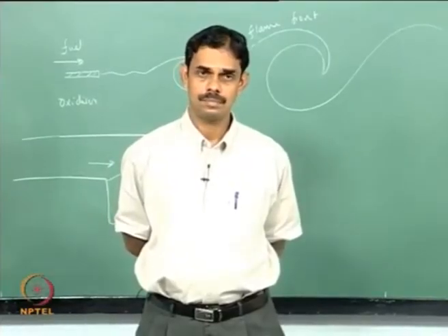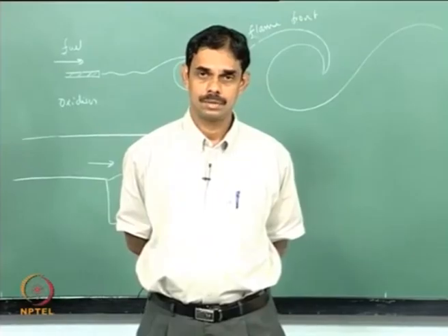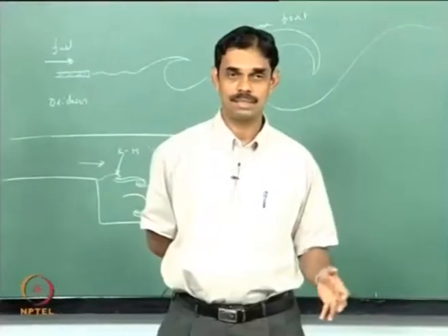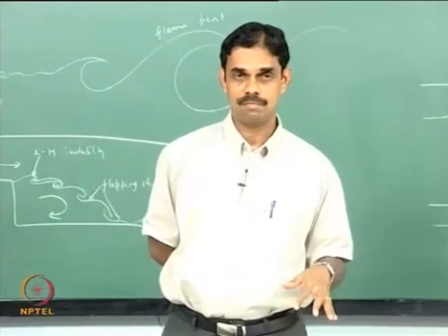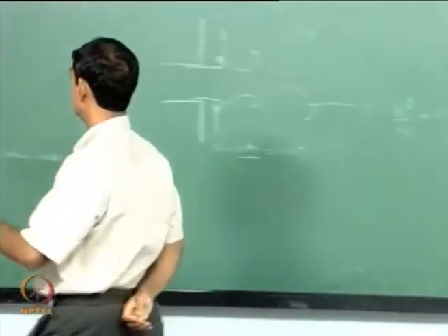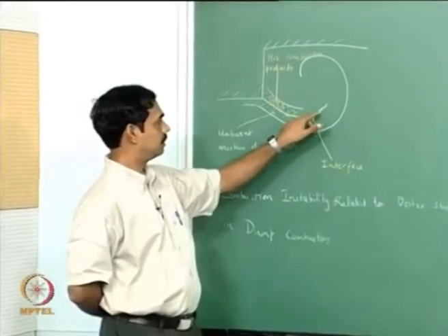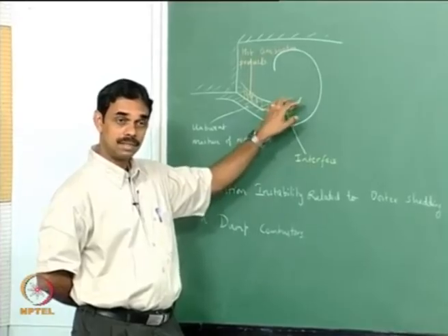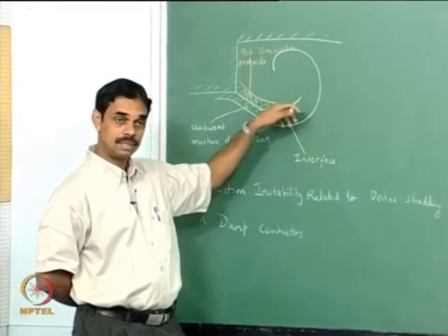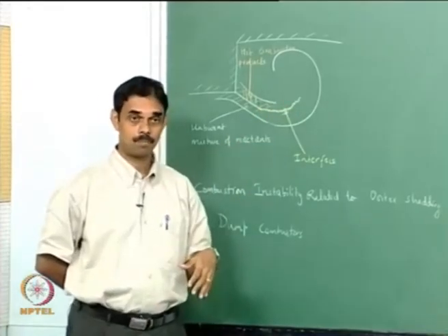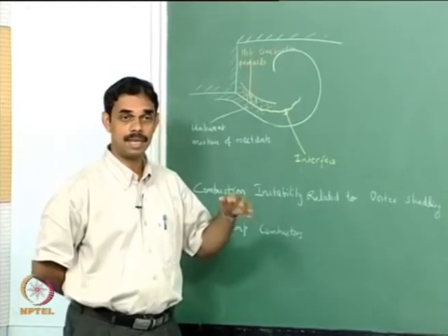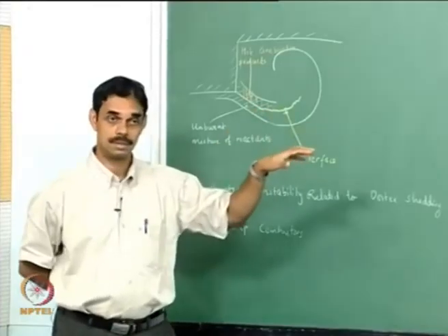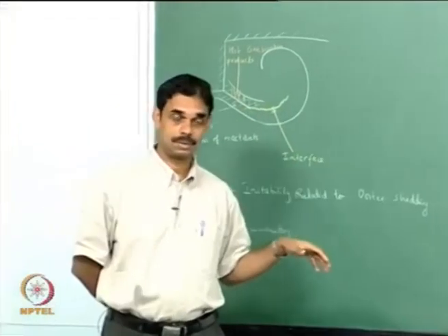When you have a Kelvin-Helmholtz instability, why would there be small scales, like small scale mixing? Only turbulence gives small scale mixing. Turbulence has all the scales. So when you have a turbulent shear like this, you tend to make small scale mixing, because in this region strain rates will be very high, and so you have small scale mixing, and the chance of the large vortices breaking down to small vortices. If you have high velocity gradients, or high strain rates, you can have small scales. So essentially those vortices have to break down.